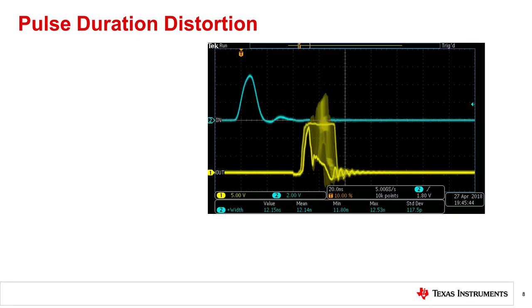Pulse duration distortion in gate drivers depends heavily on design trade-offs and the isolation medium. The D-glitch filter has a measurable impact, since it is designed to reject pulses shorter than a minimum cutoff value. But since the impact is limited to duty cycle extremes, D-glitch filter distortion is not usually included in the pulse duration distortion value in the datasheet. Lower-cost opto-isolators can suffer from poor pulse duration distortion because the turn-on and turn-off times of the LED and the photodetector are not always symmetric, more so over temperature. Opto-isolators' pulse duration distortion ranges from hundreds of nanoseconds to tens of nanoseconds.